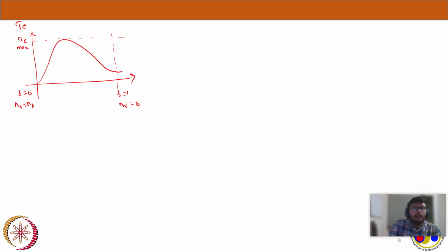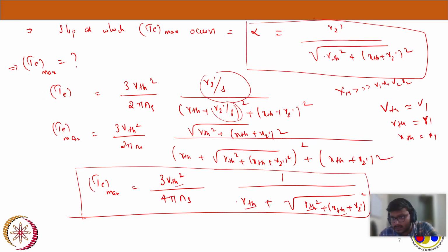Okay, this is the maximum torque I have occurred at the alpha. Now I have changed the rotor resistance. Now my R2 dash has become R2 dash plus R external. Do you think my curve changes? Do you think my maximum, the curve will change, but your maximum torque won't change, because the maximum torque expression, your R2, it's not dependent.